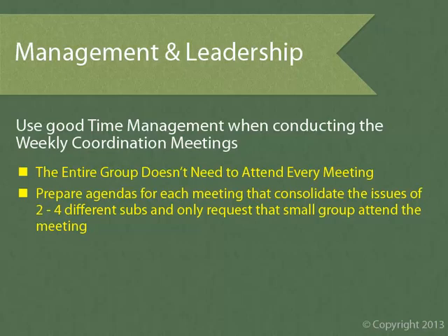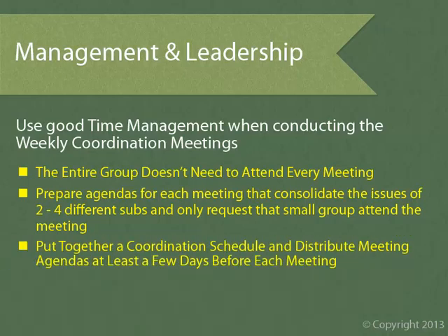Now you'll have occasions when larger groups and even the entire group needs to attend the meeting. As you get closer to the end of the coordination process, you'll find the groups getting larger and larger, and the time spent on each individual detail getting shorter and shorter. Put together a coordination schedule and distribute meeting agendas at least a few days ahead of each meeting. We don't want the subcontractors showing up to meetings wondering what we're going to cover. We want them to know what we're covering well ahead of time so that they know what to be prepared for. This is crucial. If a sub comes to a meeting and responds, "I'll look into it," repeatedly, it means they aren't prepared. They must have looked into it prior to the meeting, otherwise they're wasting everyone else's time.